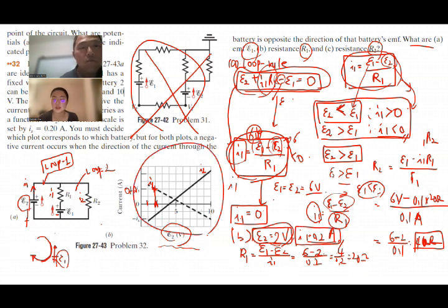Okay, and is this the same thing for part C? Yes, the same thing. Where is that? C. I chose 6 volt. I1 is 0, right? Yeah. No, that's the 6 too. Let me double check. I'm sorry, the E2, the 4 volt. If you choose 4 volt, then I2 is 0, right? It just comes across the 0 value. So I2 is obviously 0, and I1 is 0.1 amps. But you can choose 5 volt or 6 volt, it doesn't matter.